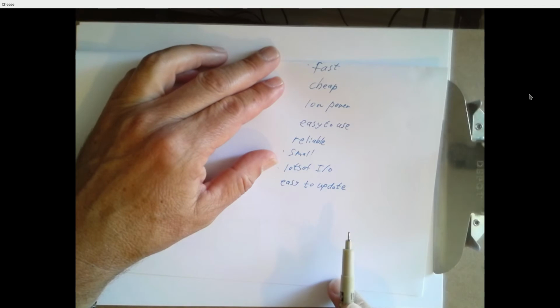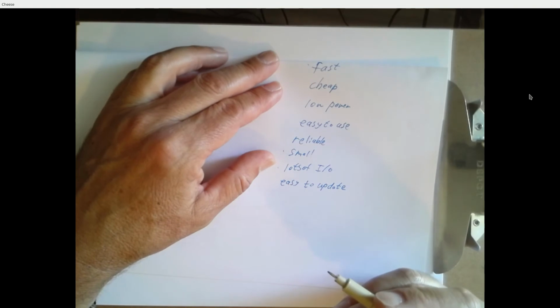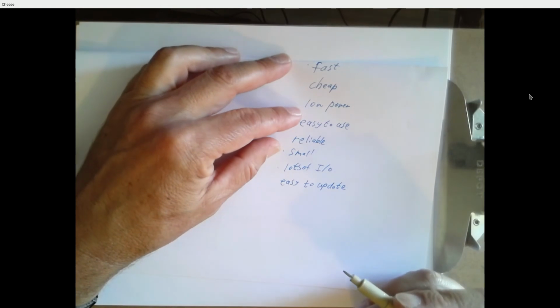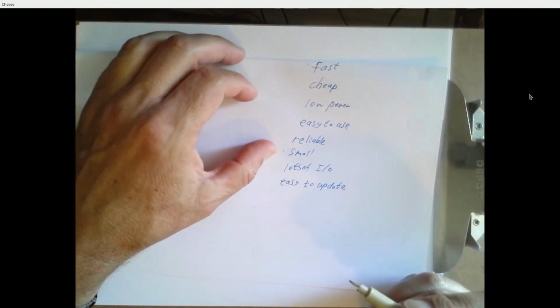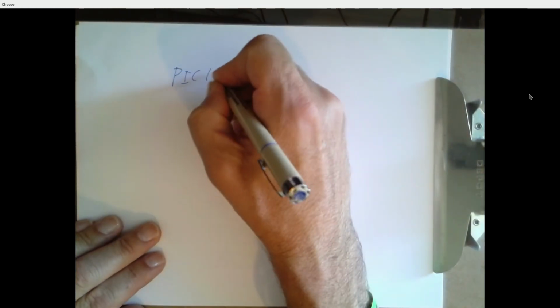What do we want to do with this processor? Do we need it to be very fast because it's going to be crunching numbers in some mission critical operation? Do we need it to be very cheap because we want people to buy these things? Do we want it to be very low power because it's going in a smartwatch? And so on and so forth. So the processor we're working with is made by Microchip and is called a PIC 18F1220. That's one particular type of processor, but Microchip makes hundreds of different PIC processors, each tailored for different kinds of criteria. So this is the one that we're working with. Now, like every chip that we work with in Engineering 250, there's a data sheet to go with each of these processors.